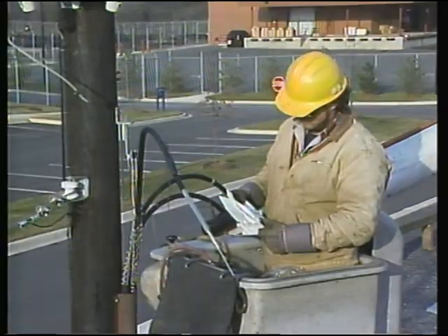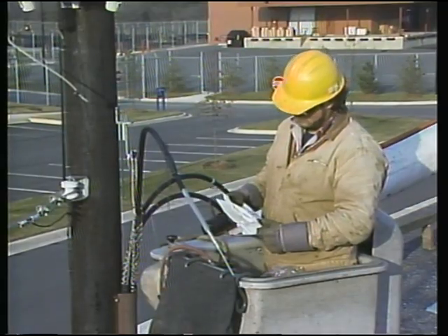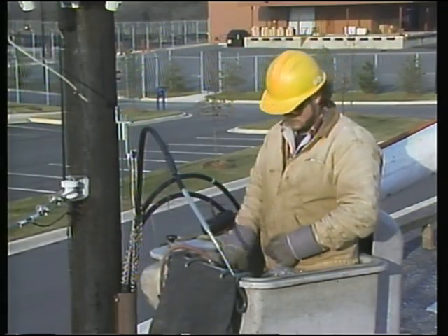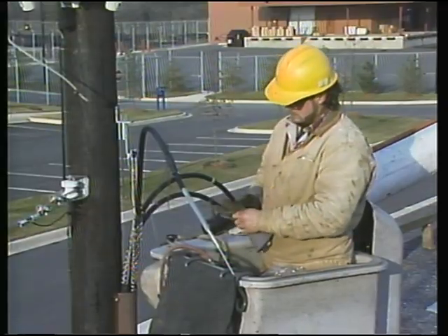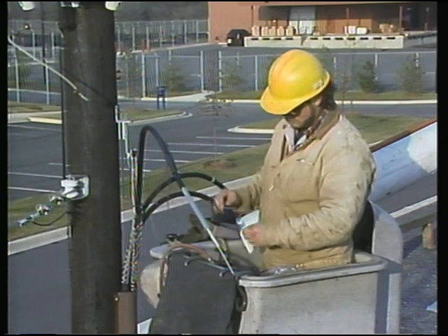The last type of rubber termination that we'll look at is applied using heat shrink tubes. Heat shrink tubes are made of a material that shrinks down when it's heated. Like the cold shrink tubes we've seen, this heat shrink tube works by the capacitive stress control method. Let's see how it's applied. As with all kit terminations, an important first step is to read and understand the kit instructions. Here, the cable has been prepared and the connector lug has already been installed.